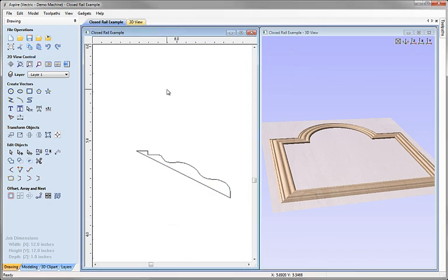So the key lesson from this is what we actually want is what we often refer to as a leg running down the side here in order to give it its proper vertical depth. When you draw a cross section, it's effectively got to be like you've done a cutaway through the part that you want to sweep around the shape. So this line that I've just drawn in there, this vector line, we can actually use in order to help us construct this leg here.